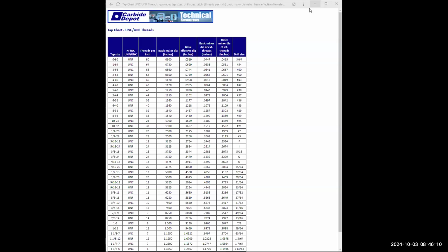Now, type in L. You don't have to keep going up here selecting line. You can type in the letter L. Enter. Now watch what happens. See how it snaps to the side of the circle. Click. And I want you to drag a line just like this all the way down. Click. Enter. Draw another line. Look, it's going to snap. Take it all the way down. Click. Enter. I don't care how long you make it. Just make sure you pass this red line here.